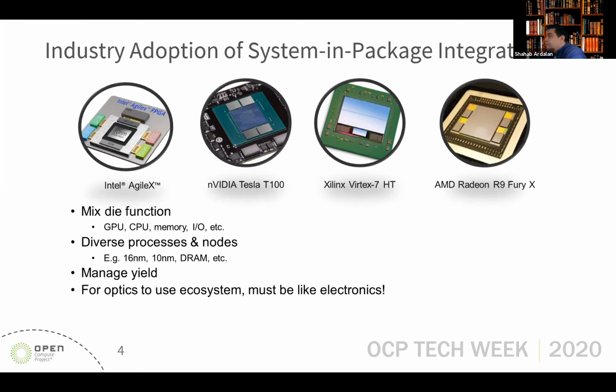But very briefly, what are the benefits of a multi-die or chiplet approach? First of all, we can use chips with different technologies and different functionalities, for example memory, CPU, and I/O, and combine them together. Each die can be in a different process node and technology, optimized for the functionality or availability of that IP. Of course, yield is going to be better because we reduce the size of the chip, and higher yield usually means a better price tag.